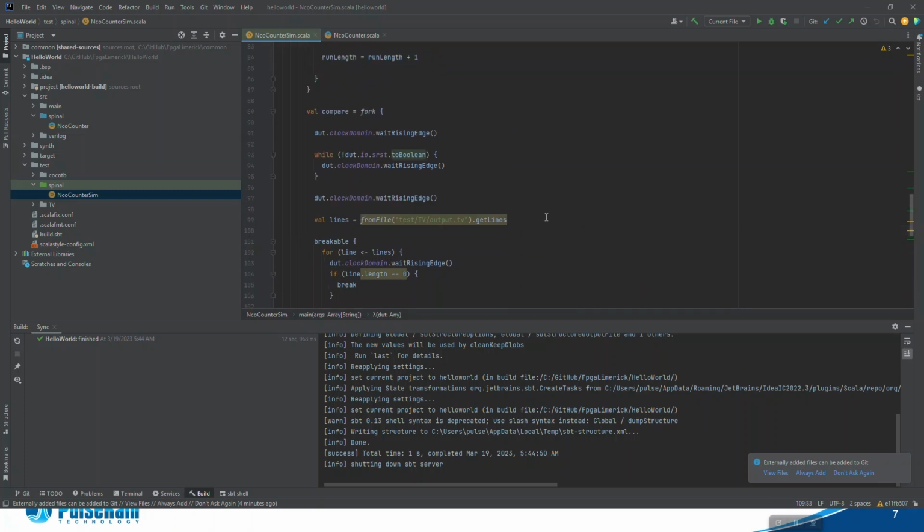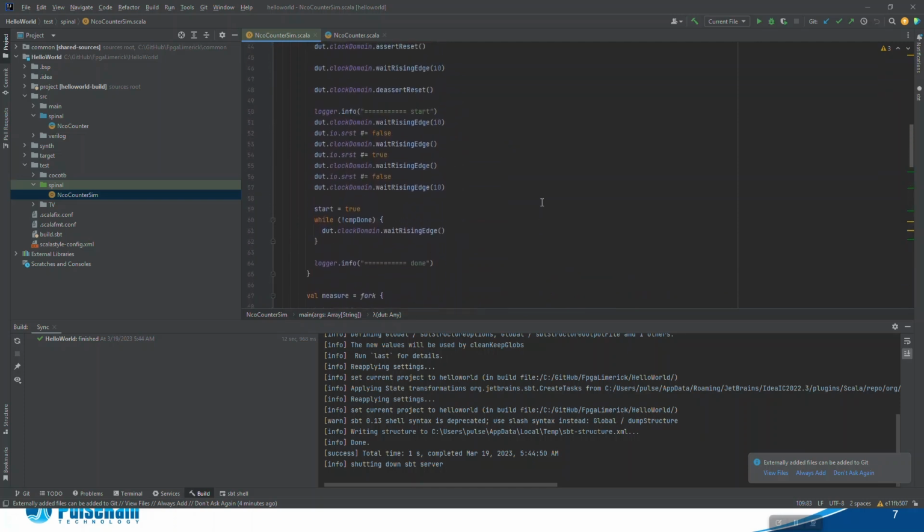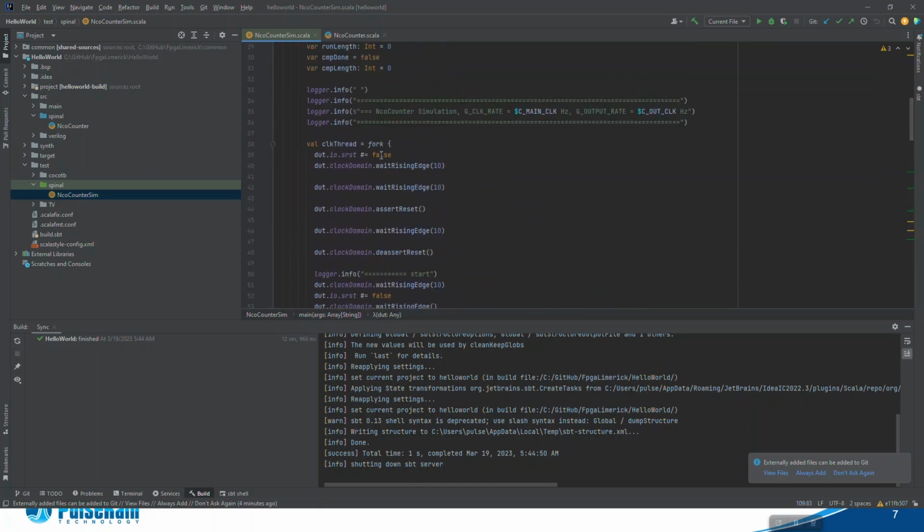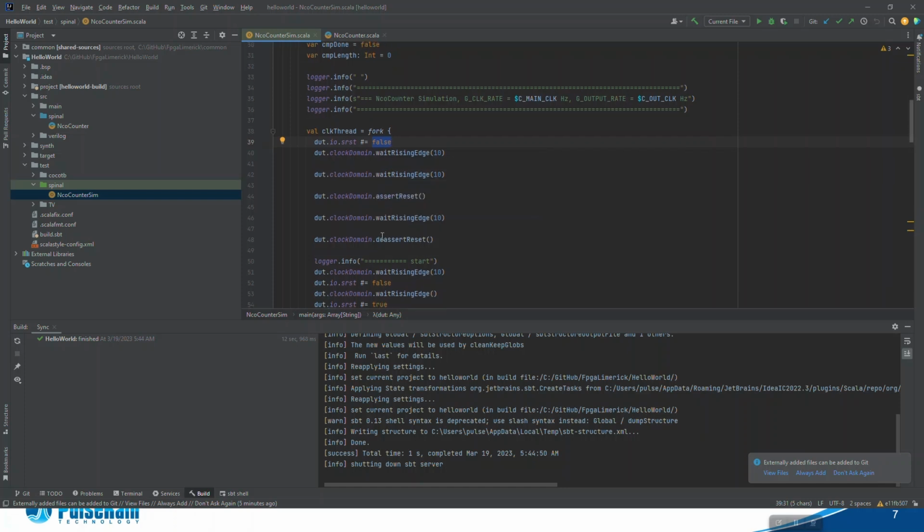And when we write Boolean values true and false to drive the inputs, they start with a small letter instead of a capital letter, because capital True and False are for SpinalHDL, and small true and false are for Scala. That's the difference. Again, please remember the test bench has to be in vanilla Scala, 100% pure Scala without any SpinalHDL. That's something we have to remember.